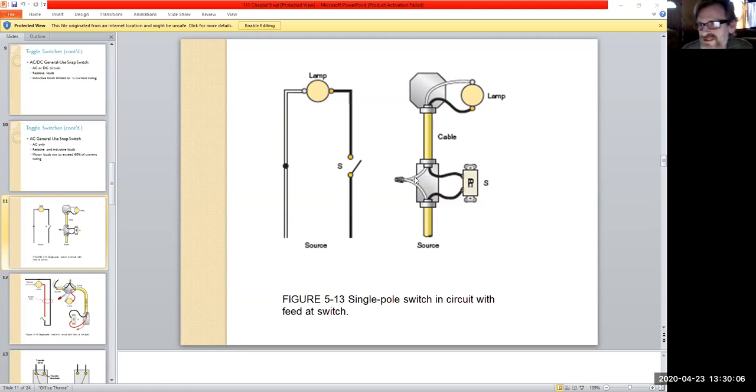Because anything over 6 inches counts as two conductors when you're stuffing a box. So if you get one of those small gem boxes, one of the utility boxes, those things are tight and you don't want to overstuff them because, oh my God, what a nightmare. But this is a pretty common configuration for wiring the switch up with a light, a lamp, lumen.